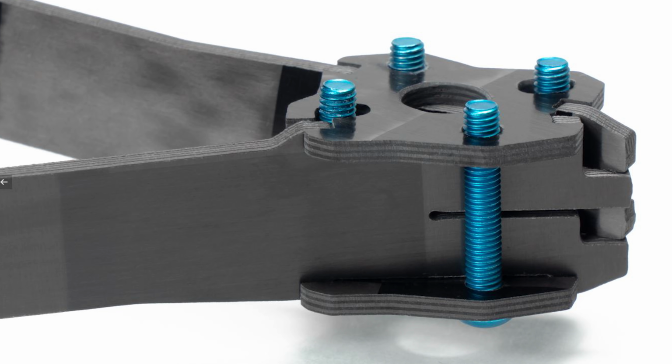And you need to wait a fraction of a second before you start moving your nozzle because you need to start the sand feeder, so that you have the mixture of water and sand correct before you start moving. Otherwise, you get this delamination once again, and this takes close to a second or something like that. And this second costs you a lot of money because you have so many holes.